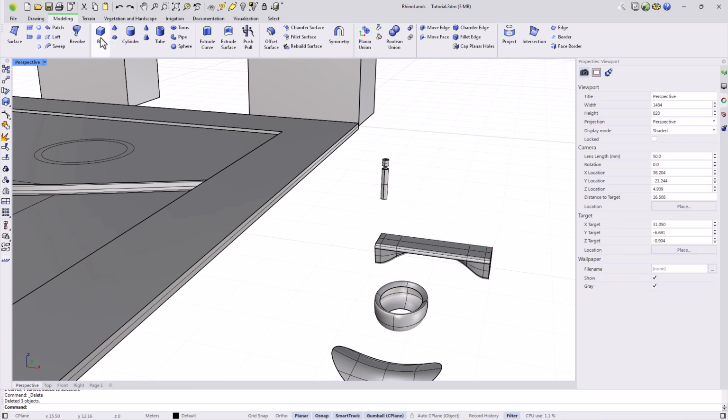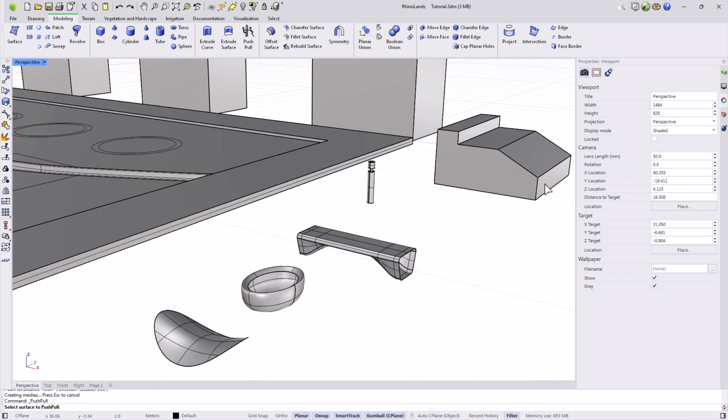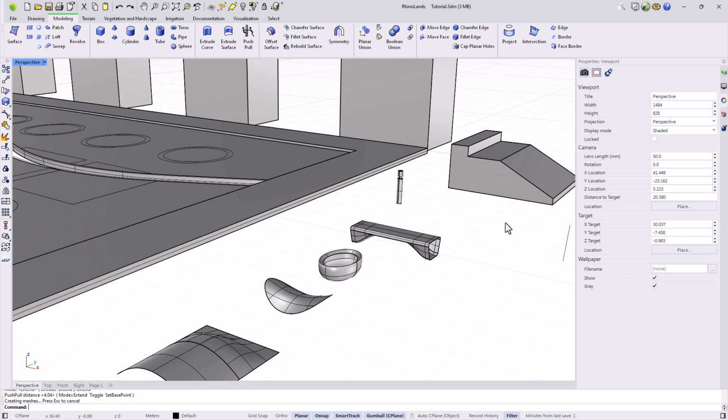push or pull is a very useful tool for editing solids, adding or subtracting volume in specific areas. This tool automatically detects the faces of a solid and also the intersections with other curves. By clicking on a face or segment with the cursor, it allows us to move the face to create new extrusions or cuts, depending on the direction in which we move the cursor. With some faces in the command options, we see that the mode option appears that if we press the M key allows us to choose between extrusion or extend. And with extend, it extends or shortens the face in this way.